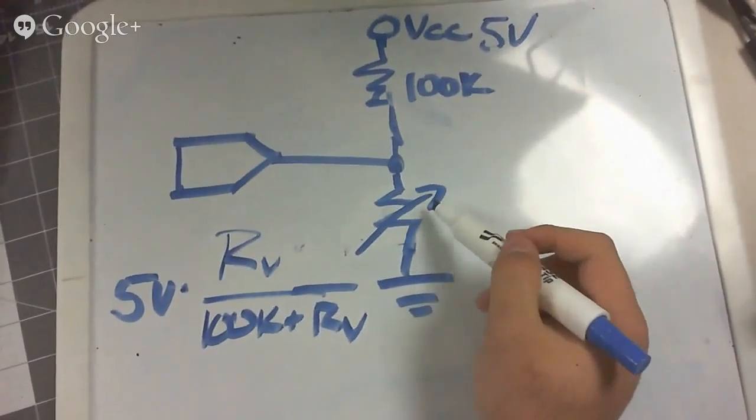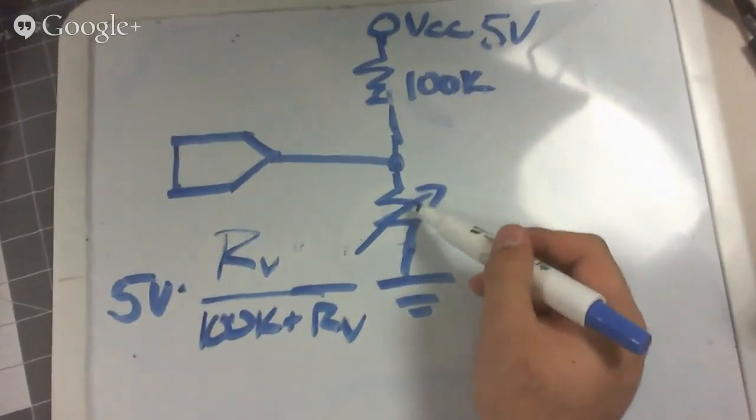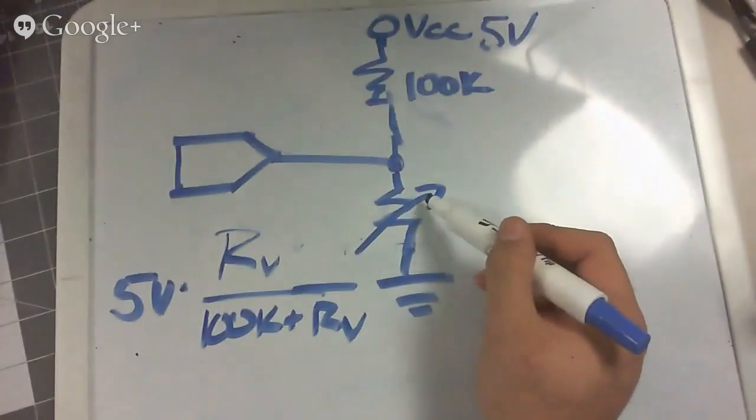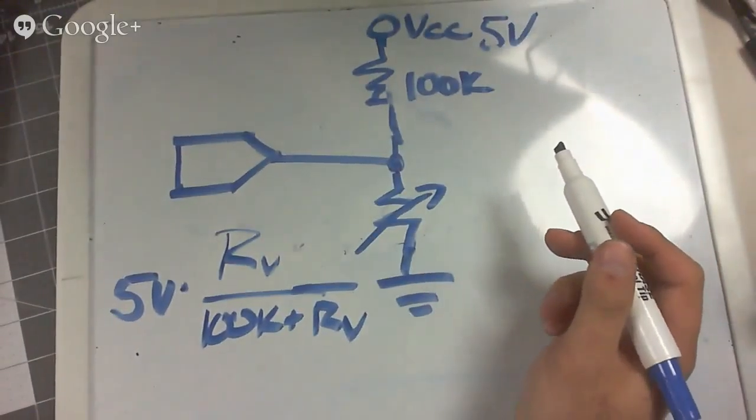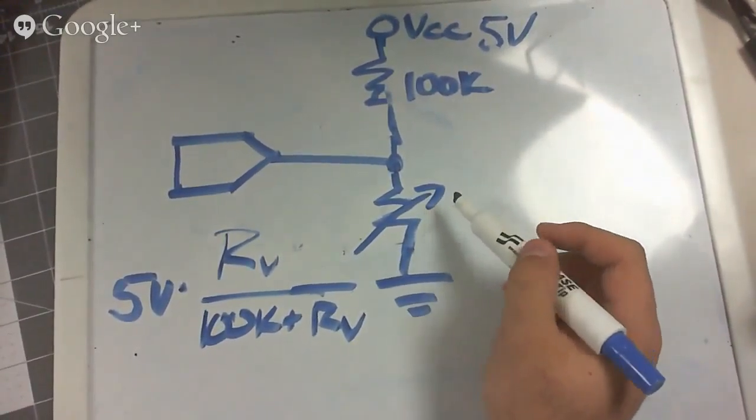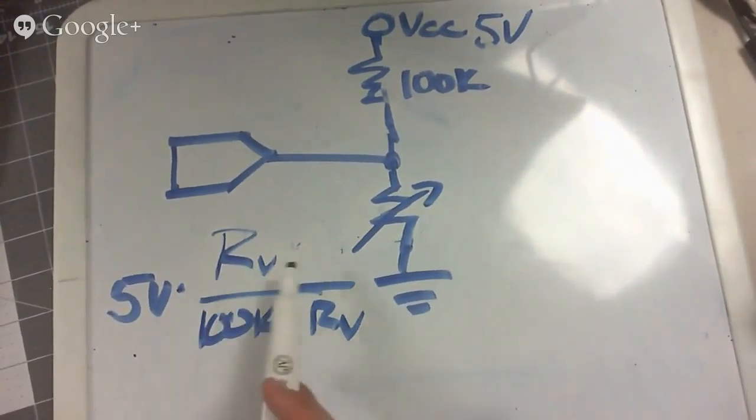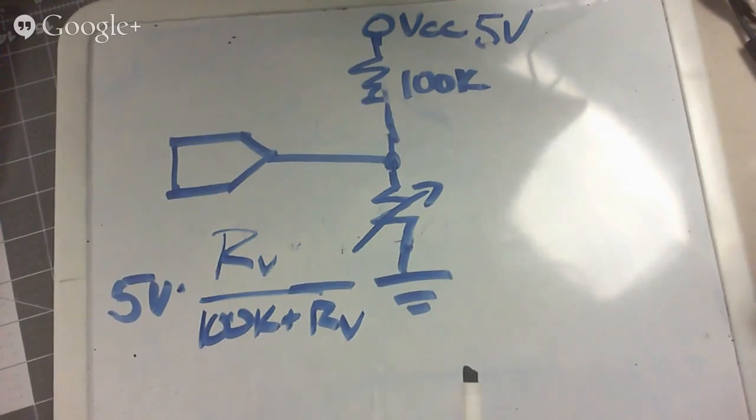So now what happens? I crank this down so I've got a really huge amount of resistance across this. Let's say this thing's capable of doing mega ohms worth of resistance. So huge resistance over a huge resistance plus a little bit, this kind of just doesn't matter anymore. So it's basically big over big.